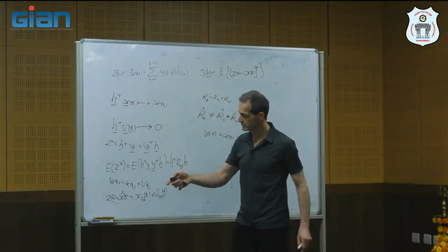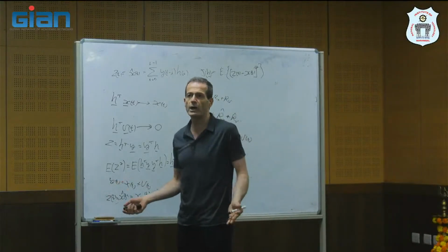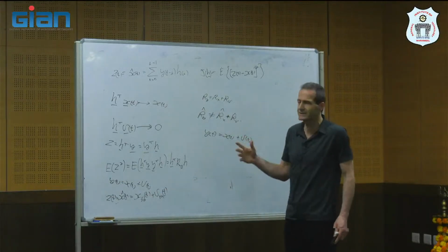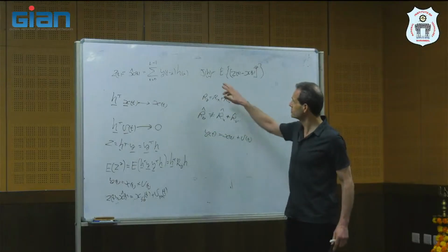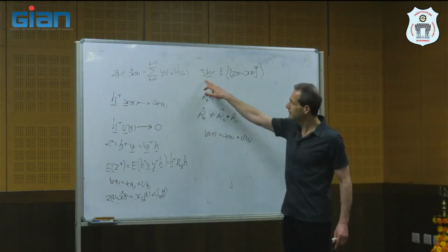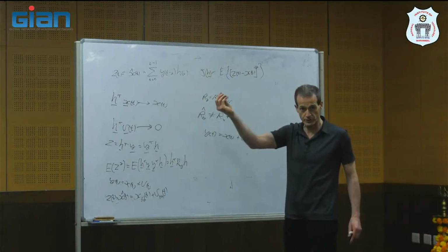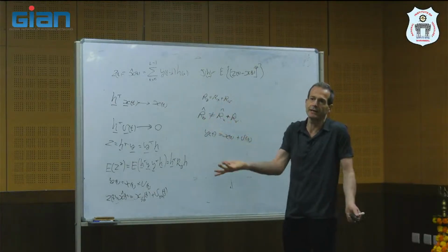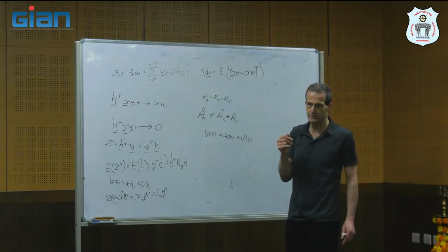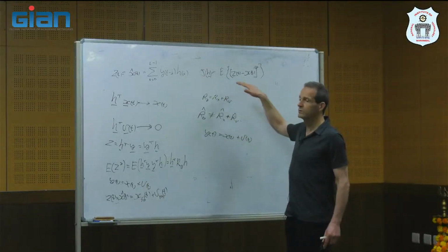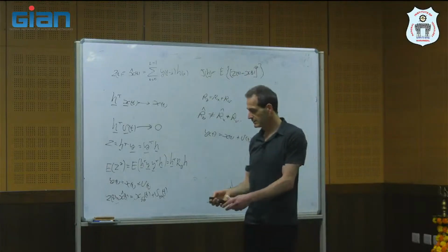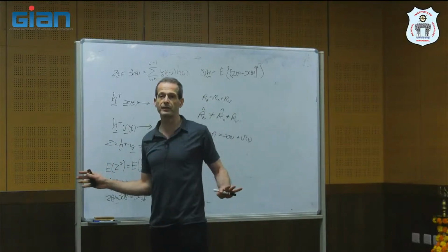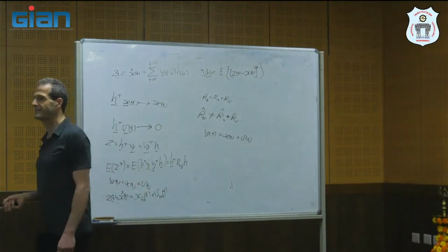So H, the filter, goes to 0. Why? Because X is negligible. You don't have any desired signal. So it's better just to suppress the residual noise, because the mean squared error has two components. One is distortion, one is the residual noise. But the distortion is not important because you don't have X. It's negligible. So it's better just to remove or suppress the residual noise by equating the filter to 0. So you suppress everything because you don't have any signal over there.